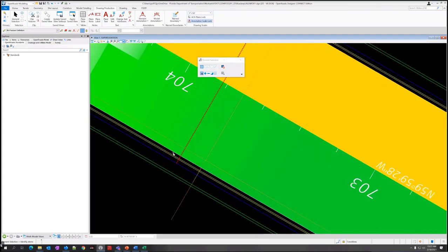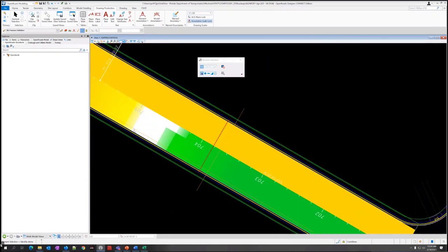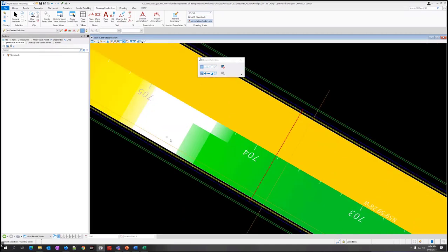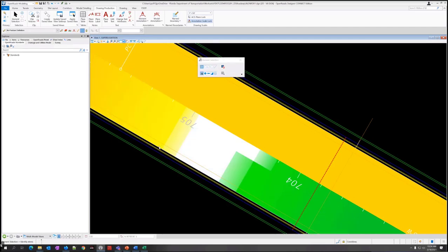If we create that curb lane manually, we're just going to say the default slope of the curb is actually 9.375, this direction. And then the transition is going to happen a little bit differently. It's not going to be that long. You don't want your long, flat stretch of gutter. But by the time this starts to get into positive super elevation, that's where the gutter needs to match the slope. So by the time you hit 0, then it should be rotating with it.